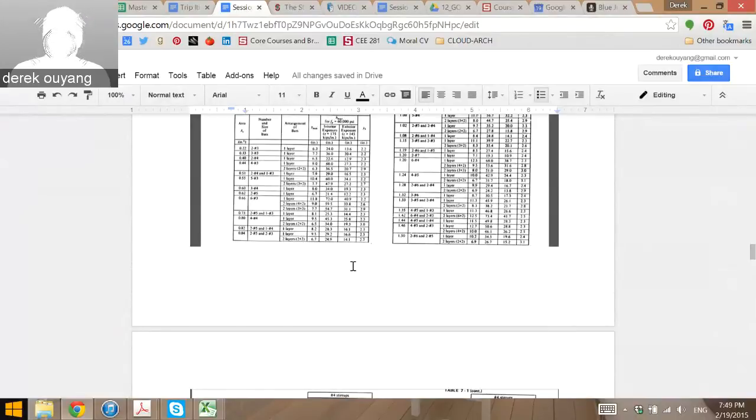You know that, and then really your only variables are B, D, rho, and Mn, right? And so what you've done, hopefully, is you put BD squared on this side, and then you put everything else on the other side. Usually, given a rho, you can actually get a real number for this. So let's say it's just 6,000 for a given problem because you know the capacity you want to design for, which would be Mu, and then you know rho, let's say we estimated it as 0.018 F prime C or Fy, something like that, right? This is a nice assumption to go with that hopefully Lepic has shown. So you get a number here.